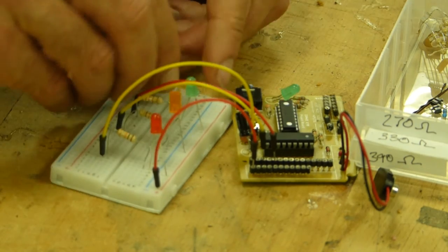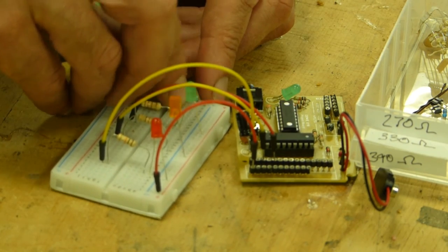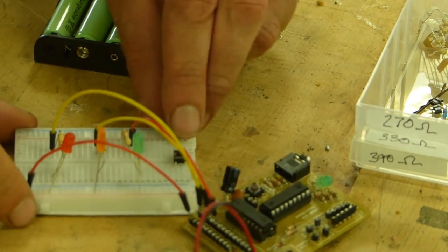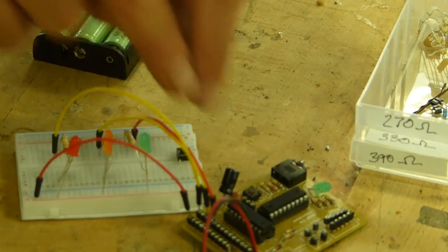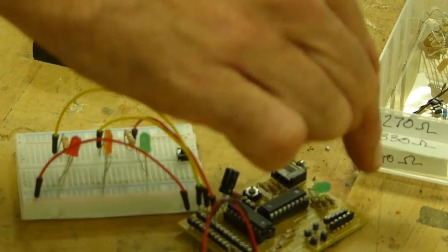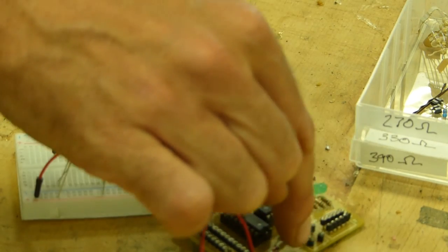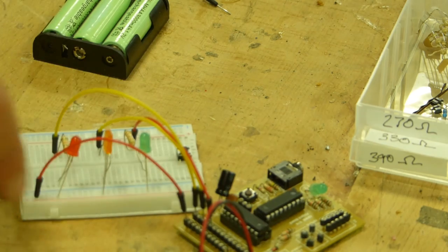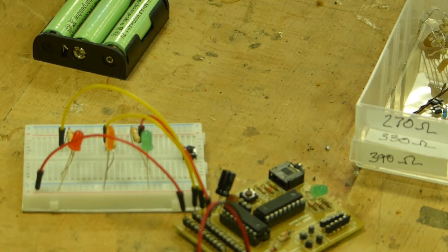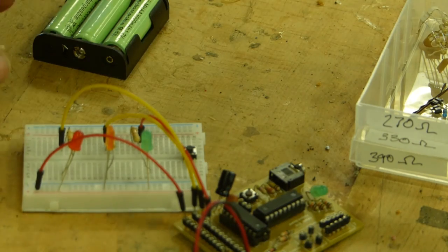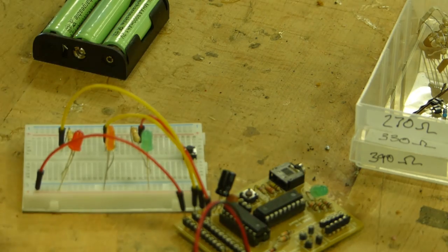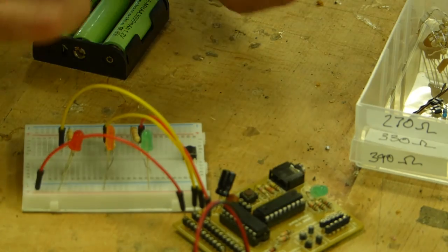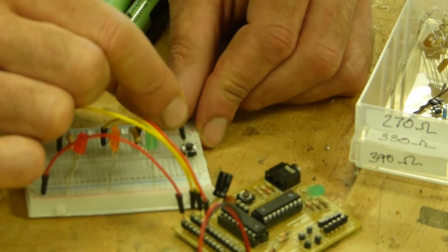So we're going to put that one there, straddle across these two columns. If you can just about see that, the two narrow legs go straight down into separate columns. Now these plus volts here are the same as these plus volts here, so I can just use the same rail across. I've run out of colour coding, but if you're going to do a complicated circuit, I do recommend putting black wires in for minus volts and red wires for plus volts. Just makes things easier to recognise what's going on.